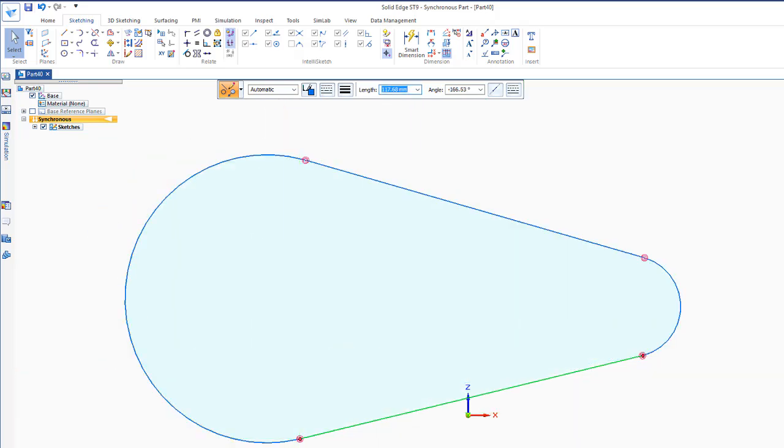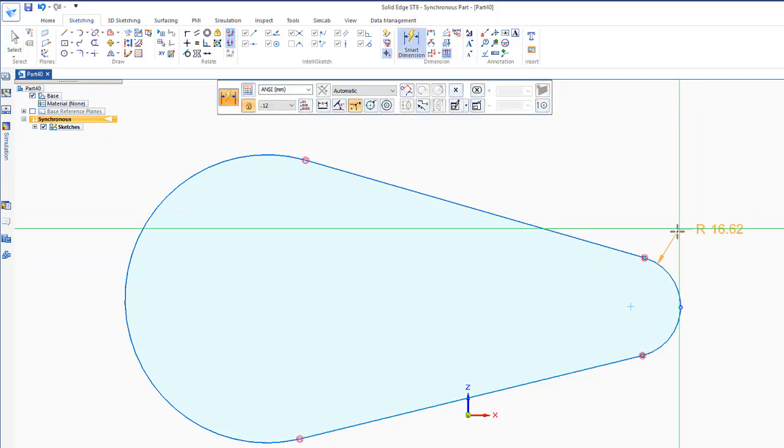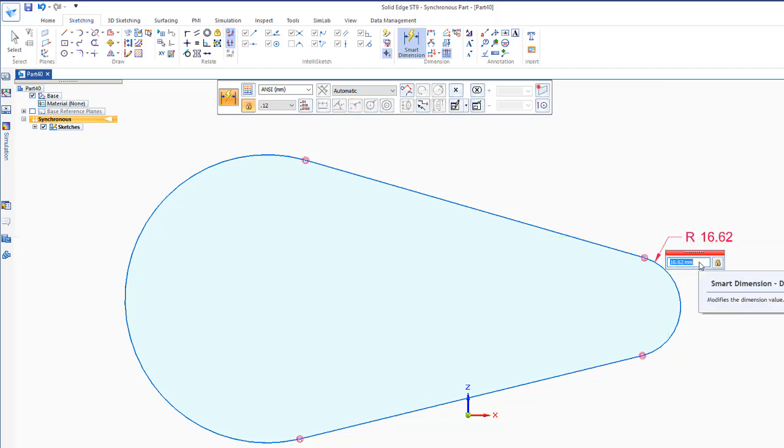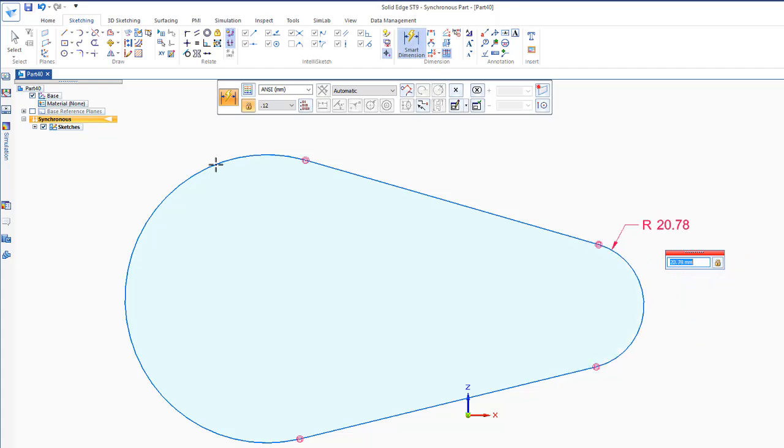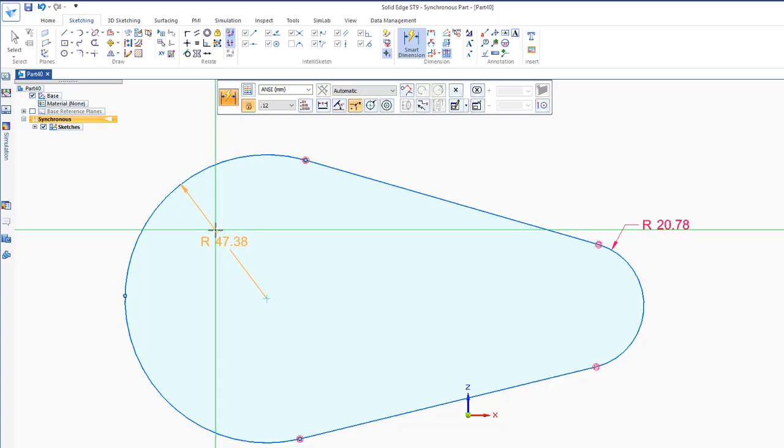Now usually after you've applied all your geometric constraints, that's when you go and add dimensional constraints. And you can just push the cursor in to where you see the dimension and roll this in or out. But again, this is when you start to add your dimensional constraints and say I just wanted that to be 50.